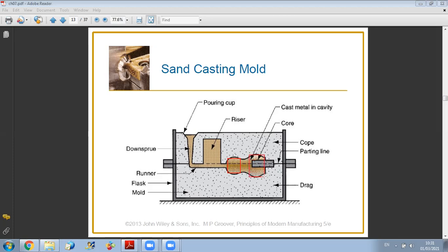If we don't have uniform geometries, then we might have variable solidification times in different regions. So here, for example, the solidification time is higher because the volume to area ratio is higher. When you put the riser close to this region, the molten metal can be supplied first to the far zones. They will solidify. So solidification will start from here and will continue in a directional way from the far zone towards the zone close to the riser.